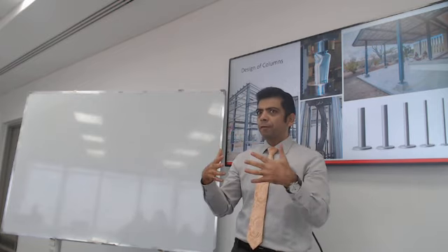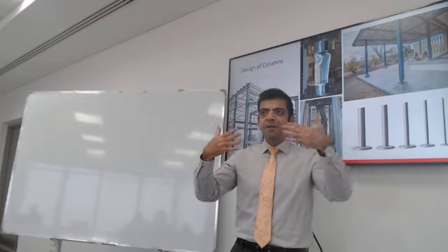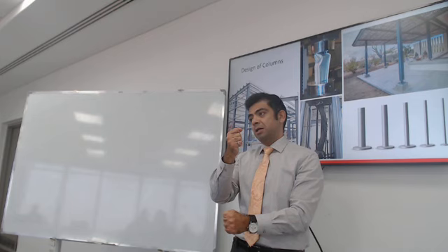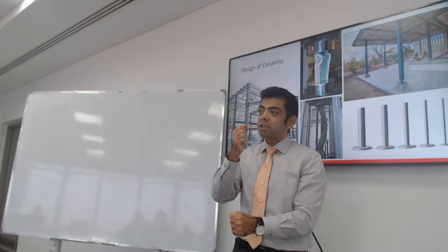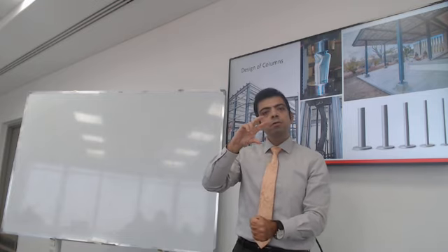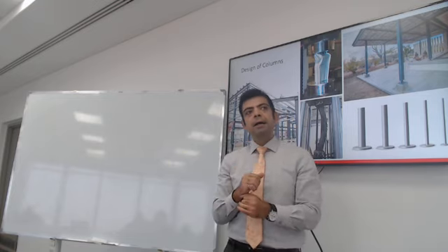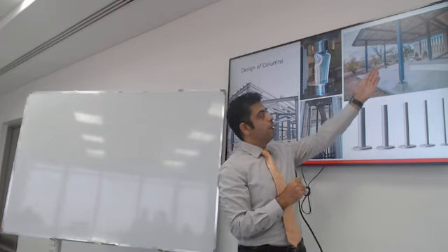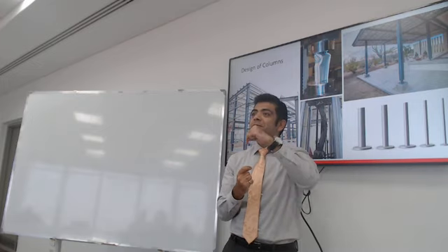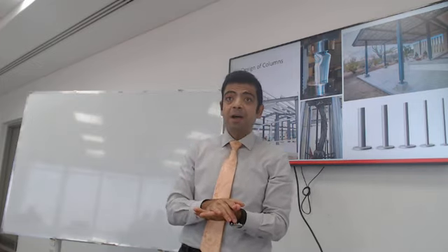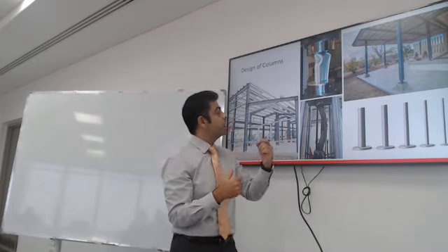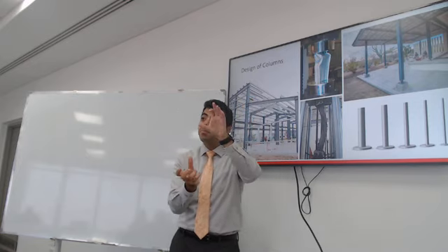Here is the rule of thumb. Beams are usually designed for bending and shear. Columns are designed mainly for compression. Some columns will have compression and bending, and shear as well. If you introduce bending, then you have shear. So in an example like this, most probably this column has just axial load. And this is what we're gonna deal with today. Today we're gonna design columns under pure axial load. Next week, we will deal with a column that has axial and bending.